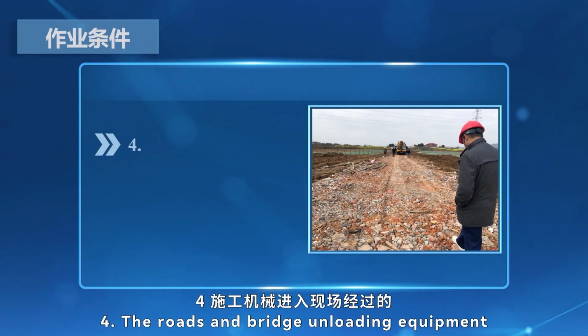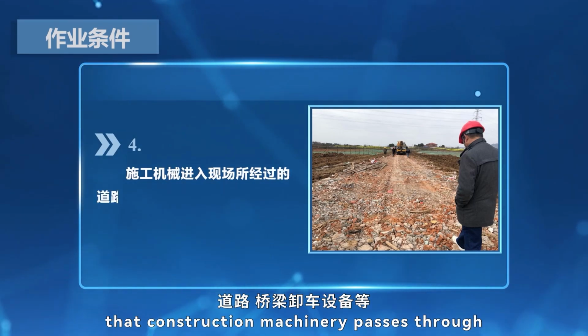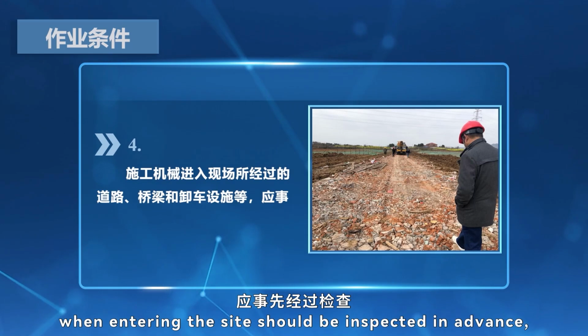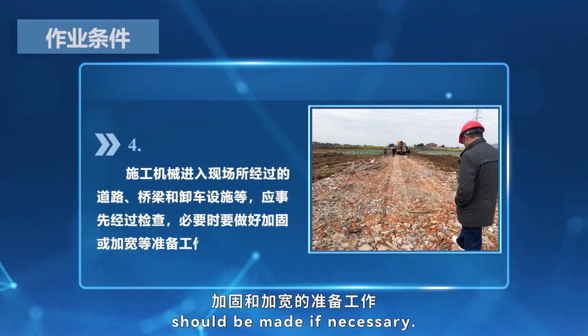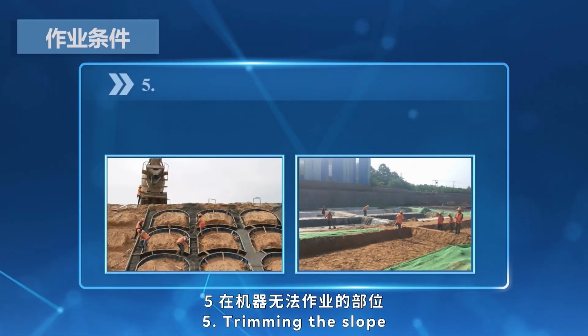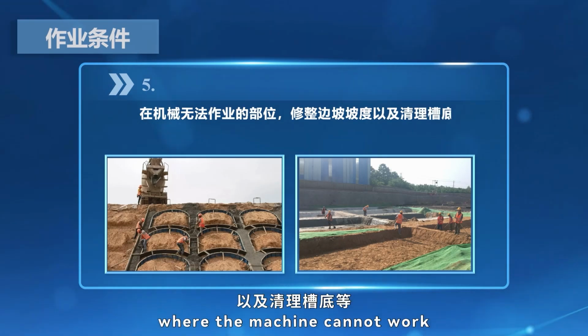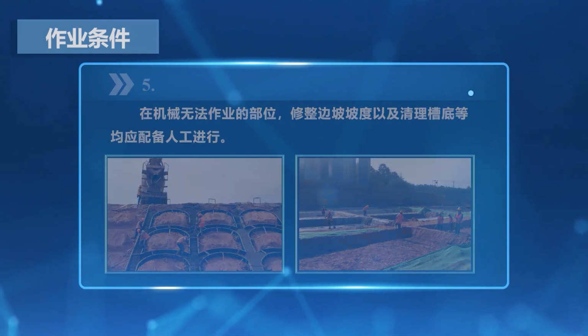The roads and bridge unloading equipment that construction machinery passes through when entering the site should be inspected in advance, and preparations for reinforcement and widening should be made if necessary. 5. Trimming the slope and cleaning the bottom of the trough in the parts where the machine cannot work should be equipped with personnel.